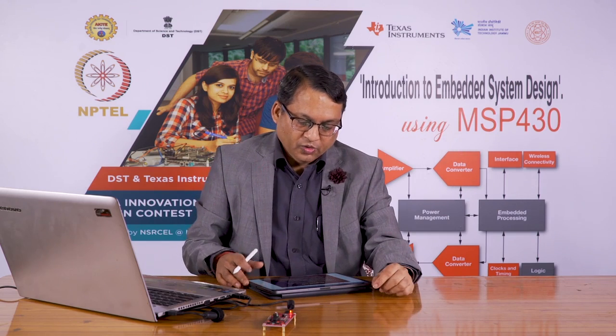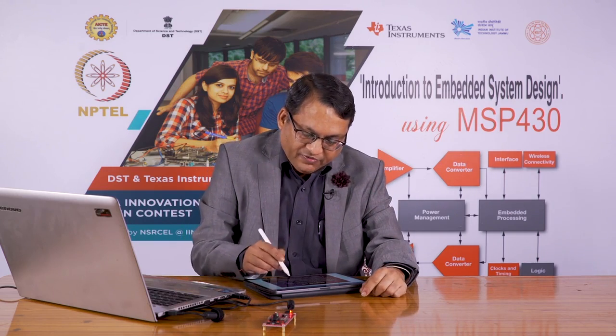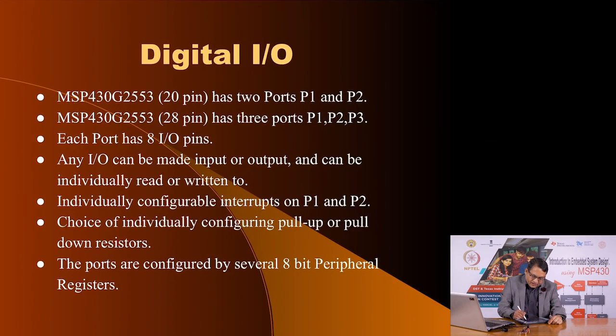Since we are dealing with the MSP430 G2553 microcontroller, which is available in two footprints, meaning physical devices: if you choose a DIP package, you will get two ports, labeled P1 and P2, and our MSP430 lunchbox has a DIP IC. In case you choose to implement your system using the SMD version, which has 28 pins, then you will get 3 ports, labeled P1, P2 and P3.